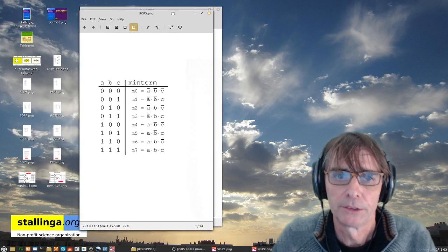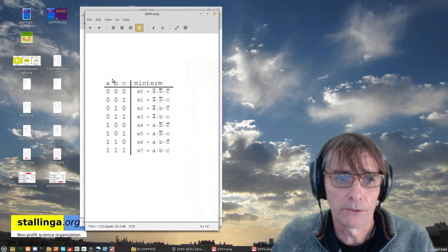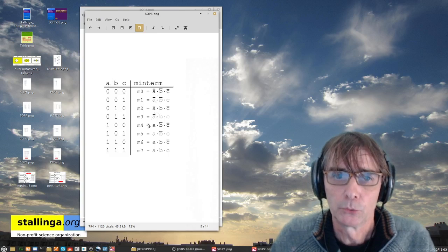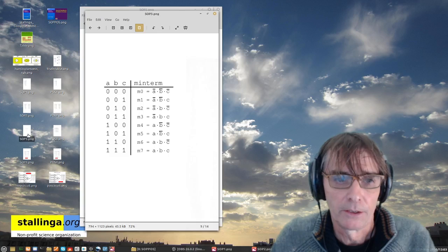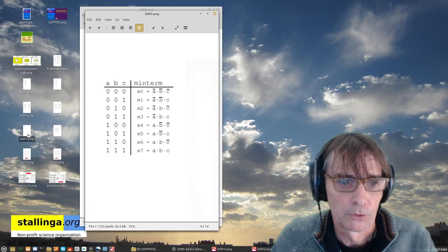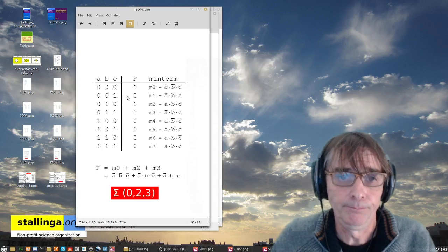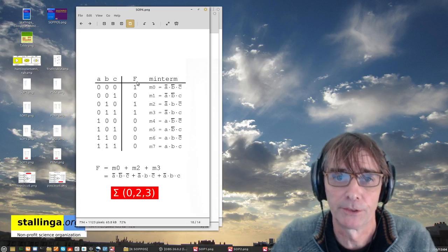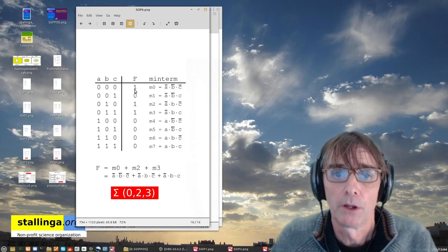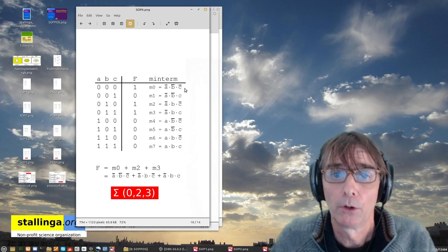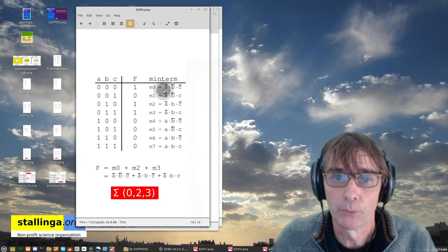So now that we know this, we can actually use an OR gate or an OR operation to implement any logic table, any truth table. And that I have done here. Imagine that we want to implement this truth table, this function f. Then what do we do? We just sum, we just OR all the min terms that have a 1 in front of them. So it would be this one, m0, or m2, or m3, and nothing more.